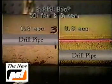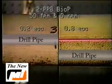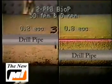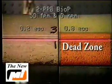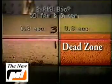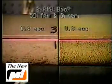This clip demonstrates how fluid flow in a concentric annulus on the left differs from that of an 80% eccentric annulus on the right. Note the flow filling the hole on the left and the flow primarily along the top of the hole on the right. In order to effectively remove the cuttings from the high-angle portion of the well, we must mechanically disturb the cuttings, either with turbulent flow, which is impractical in hole sizes over 8.5 inches, or through pipe movement.